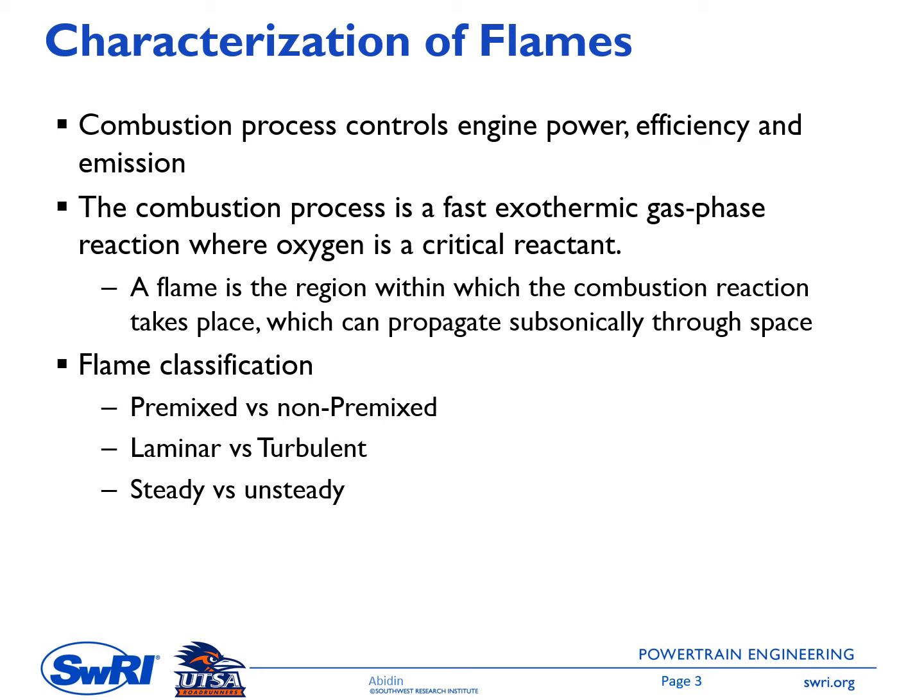And then we might classify the flame as a steady flame as well as an unsteady flame. In the steady flame, we have a steady flame structure, and for the unsteady flame, the structure of the flame might change with time. And what are the flame types inside the engine? Inside the engine, we have either premixed, turbulent, unsteady flames. This is for the spark ignition engine. Or we might have non-premixed, turbulent, unsteady flames. This is for the compression ignition combustion process.